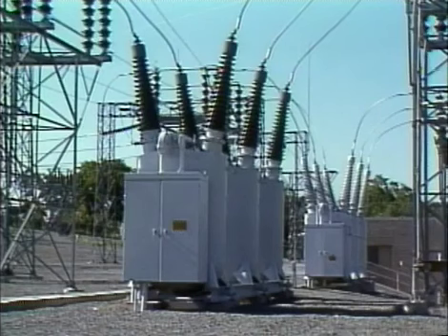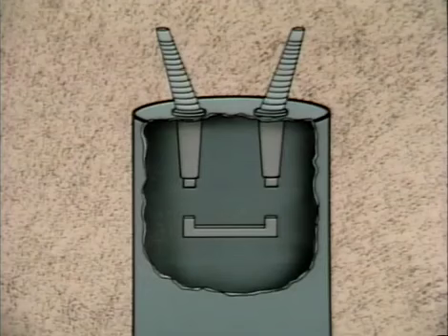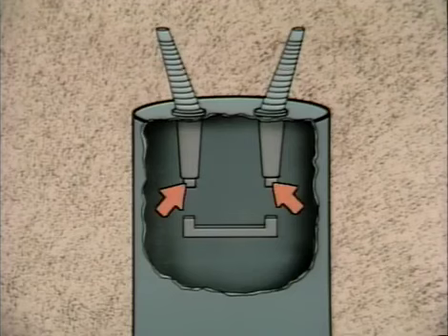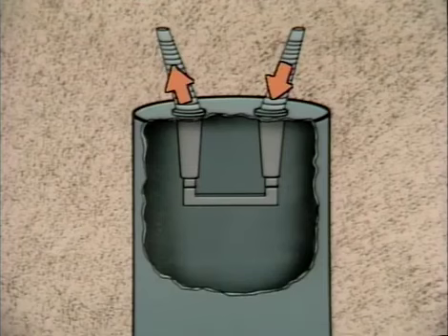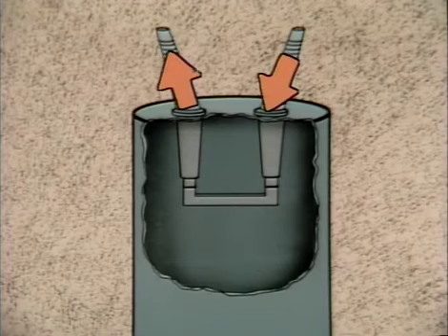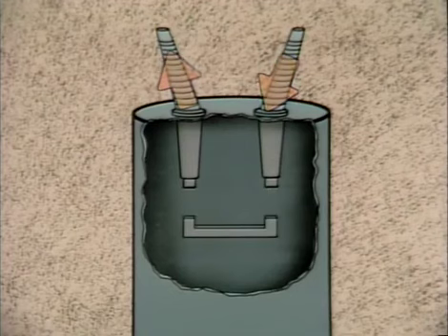A circuit breaker is an enclosed electrical switch. Like a fuse, it's used to help protect circuits from the effects of faults. Now, this simplified illustration shows the inside of a circuit breaker. These are the switch contacts. When the switch contacts are in the closed position, current flows through the breaker and on to the rest of the circuit. If a fault occurs, current rapidly increases. And when the circuit breaker detects the fault, the switch contacts automatically open. This de-energizes the circuit and prevents equipment damage.